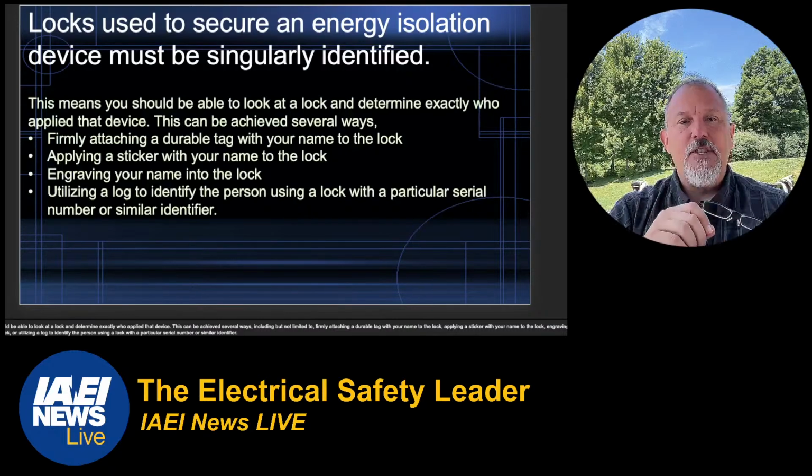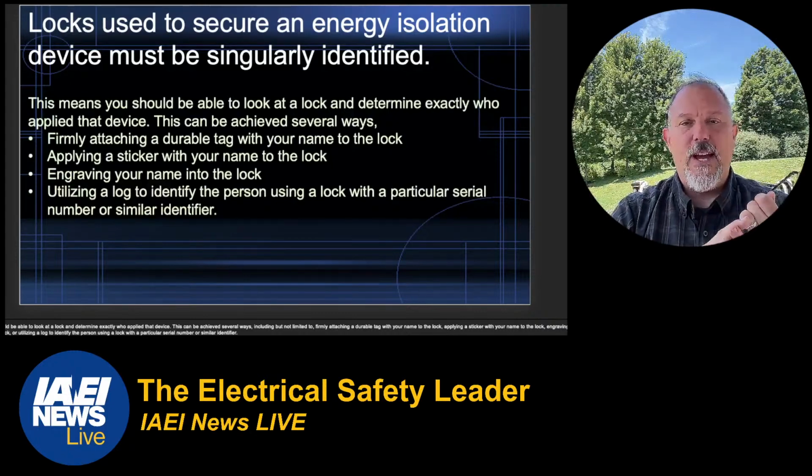Singularly identified means you should be able to look at a lock and determine exactly who applied that device. You can firmly attach a durable tag with your name. You could put a sticker with your name on the lock. You can engrave your name on the lock.